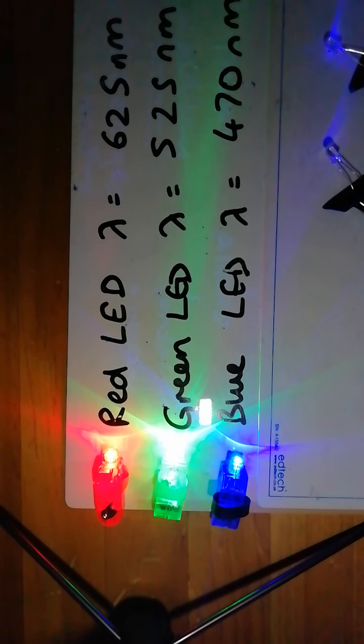So our photovoltaic cell has a difference in charge. We create an electric field across that junction, and that in itself then creates a voltage, a potential difference across the junction. And if we connect something across that junction, then we can actually have a current flowing.